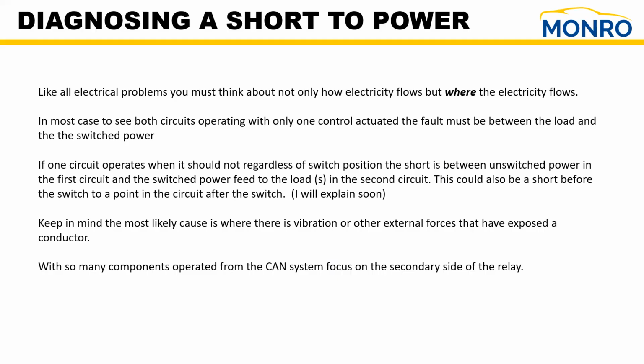And I'll explain that soon. So keep in mind, the most likely cause is where vibration or other external forces have exposed a conductor. With so many components today operating on the CAN system, focus on the secondary side of the relay.